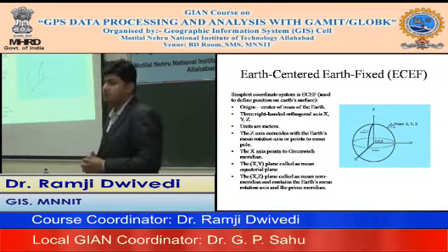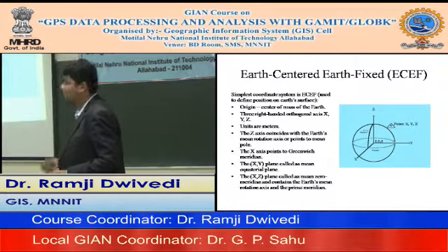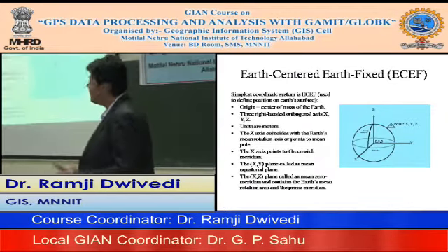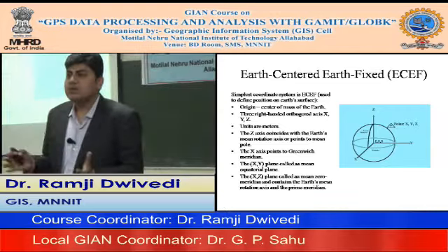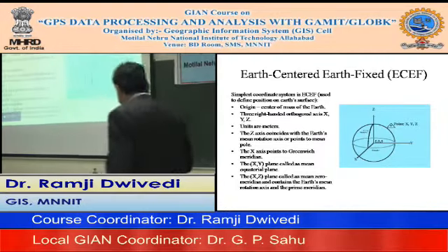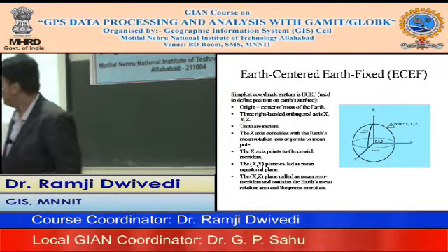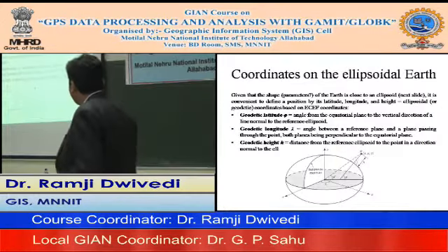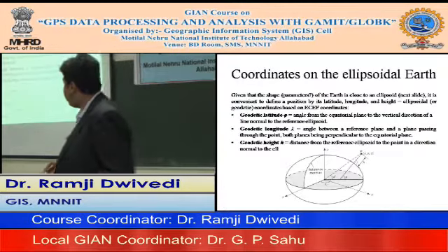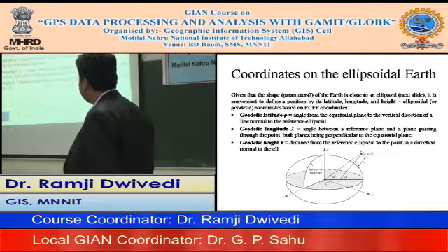The xy plane is called the mean equatorial plane, which you can see here. And the xz plane contains the mean pole as well as the reference meridian, or prime meridian, for taking measurements. So these are the fundamental planes defined for the ECEF. Similarly, the geodetic coordinate system can also be established based on this ECEF, where we project a normal to the ellipsoid, normal to the surface, which meets the equatorial plane, and this phi and this lambda we call latitude and longitude for those points, and obviously this is the height.